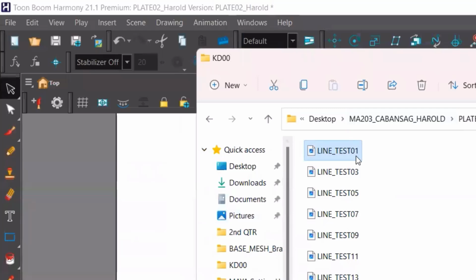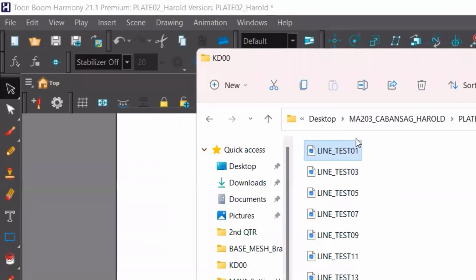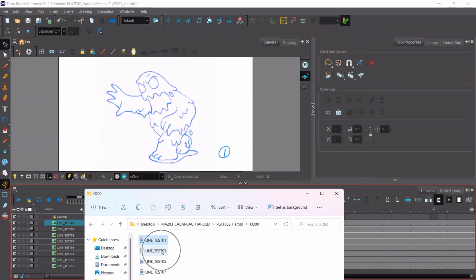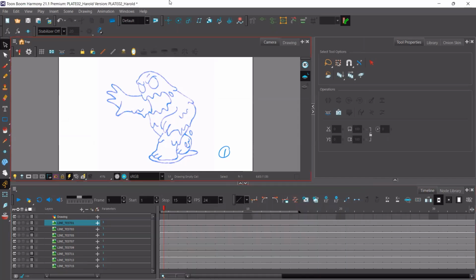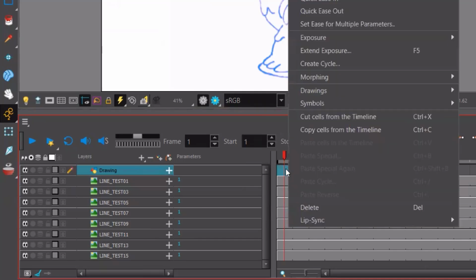What do those numbers mean, class? If anyone is listening. That number is what? Yes, these numbers are the keyframe numbers. They're not just any frame, they are the keyframe numbers. So let's say frame number 1 is a keyframe. So what I will do, for it to be marked as a keyframe, is right click here.